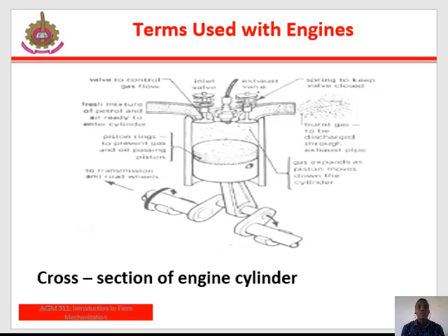We also have the engine capacity, which is the swept volume of all the cylinders, and lastly we have the engine size, which is given by the bore, which is the diameter of the cylinder, and the stroke of the engine.